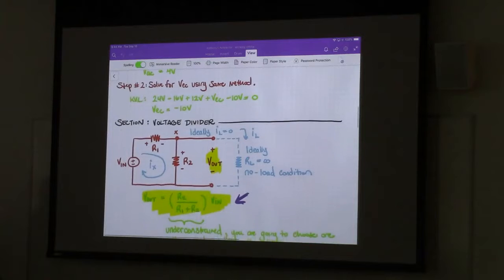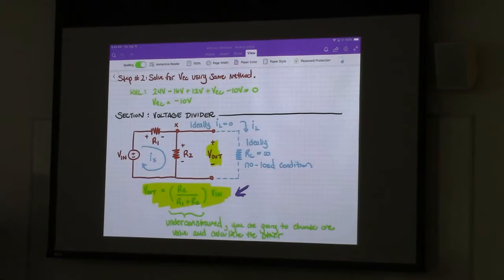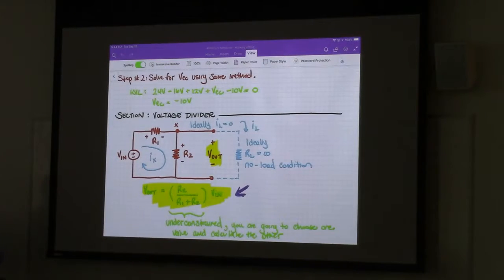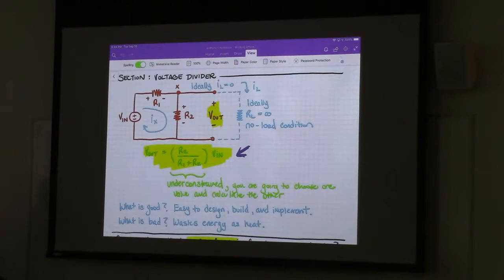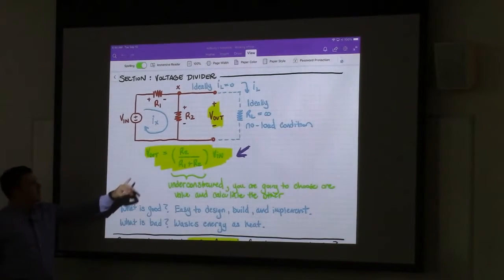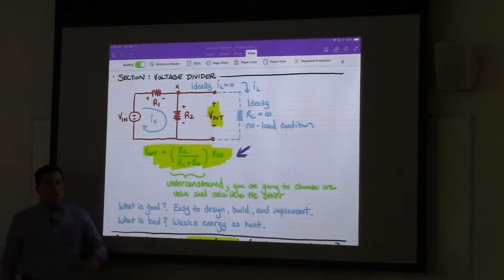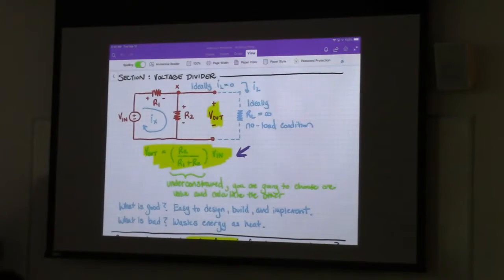The big thing that we talked about was the voltage divider. So the voltage divider is a pretty simple but very useful circuit that you're going to see a lot, especially in ENG212 lab. You're going to use voltage dividers a lot. So voltage divider, can anybody tell me what that does? The name is sort of self-explanatory. Yes. Divides voltage, right? Takes a voltage in and it brings it down to some value less than 100% of whatever it was. And the way that we determine the ratio between the input and the output is using this equation right here. Vout is equal to Vin times R2 over R1 plus R2, where R1 and R2 are defined using the schematic that's shown above.